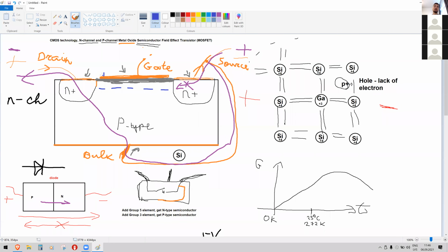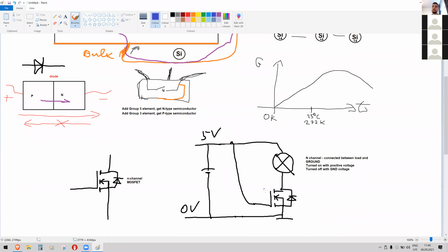Gate is actually charged positive to attract these, you enforce gate to be positive, and the channel then is attracted negative. I'll also draw it here. And the thing is, you get a tiny capacitor here. And if you just disconnect the gate from 5 volts, but don't connect it to 0, this charge stays here and the transistor stays open, right?